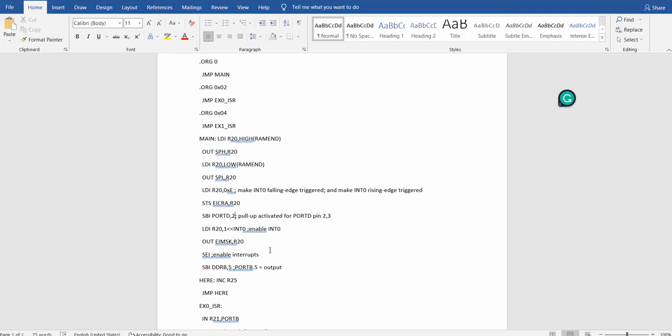Anyone? Oh yeah, this is a set bit. Set bit. Yeah. So I cannot do that on a single line. I have to copy this. Control C, and the third one should also be pull up activated. Pin 3. Yeah. Okay, so that is it.